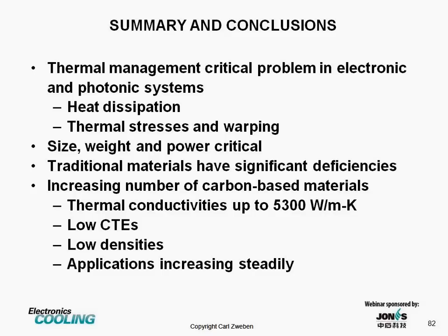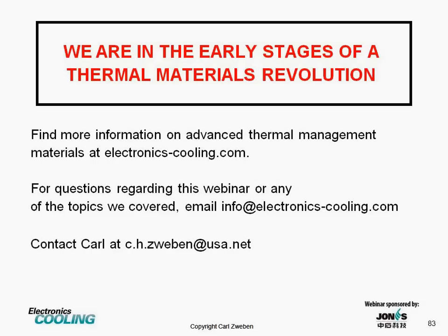So to conclude, thermal management is a critical problem in electronic and photonic systems, and that consists of two main parts: heat dissipation and management of thermal stresses and warping. Size, weight, and power will continue to be critical. Traditional materials all have significant deficiencies, and in response, there are an increasing number of carbon-based materials, with thermal conductivities up to 5,300 watts per meter Kelvin, low coefficients of thermal expansion, low densities, and applications are increasing steadily.